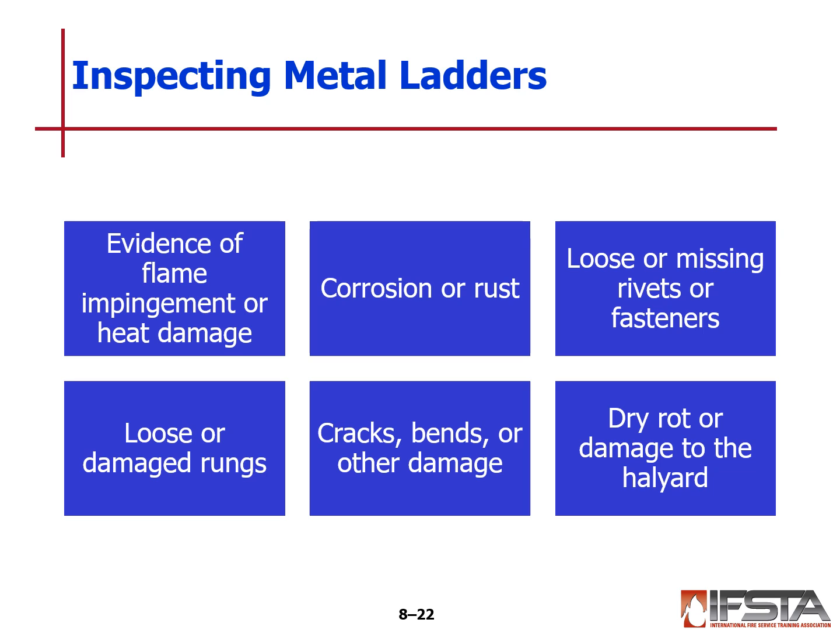Dry rot or damage to the halyard. So the halyard and the ropes that raise our extension ladders, depending on whether they're natural fiber or synthetic fiber ropes, can show damage and wear. This is the time, if we see rot, damage, or wear, that we want to replace the halyard.